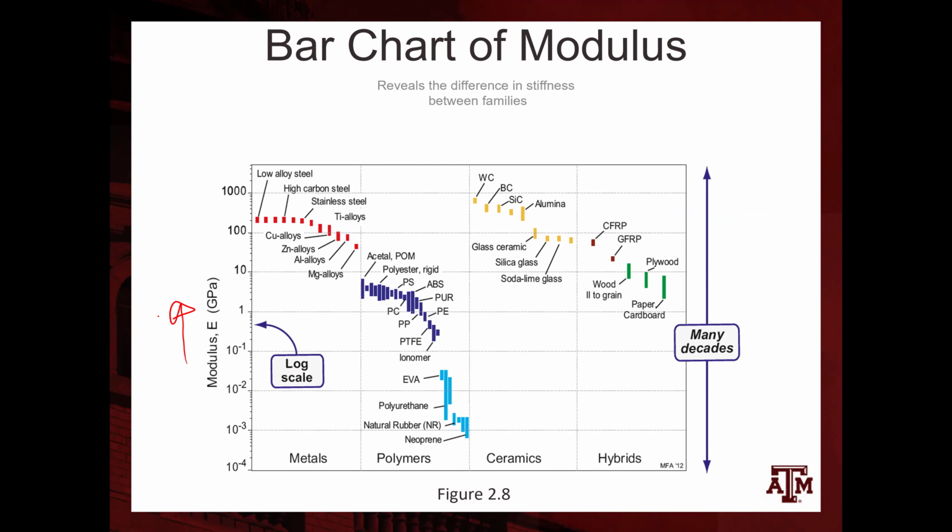So you can see that there is a large deviation, or large range, in the order of magnitude of the stiffness of materials, and that's of course easy to see or understand when we look at different families of materials. So we know polymers and plastics would be very elastic, have very low stiffness, and then metals and ceramics would have the highest values of stiffness.